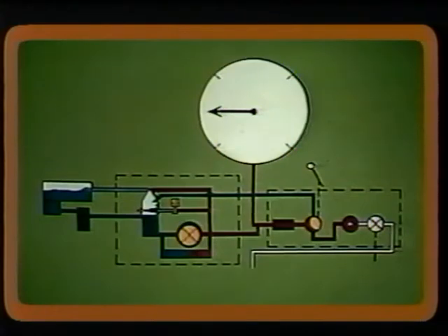And with the engine running at a low speed recommended in the service instructions, check the low unmetered fuel pressure. It must be within the tolerance specified by the manufacturer. If it is not, improper low unmetered fuel pressure can be adjusted with the relief valve.